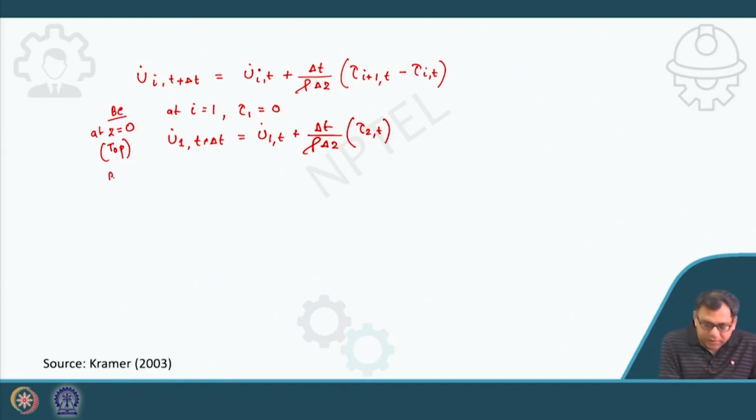Now, my next boundary condition is at the bottom. If the rock is rigid, as we have considered, the rock input motion matters, because here I go from the rock to the top. I am doing the calculation from bottom to the top, because my known ground motion is the bedrock motion.